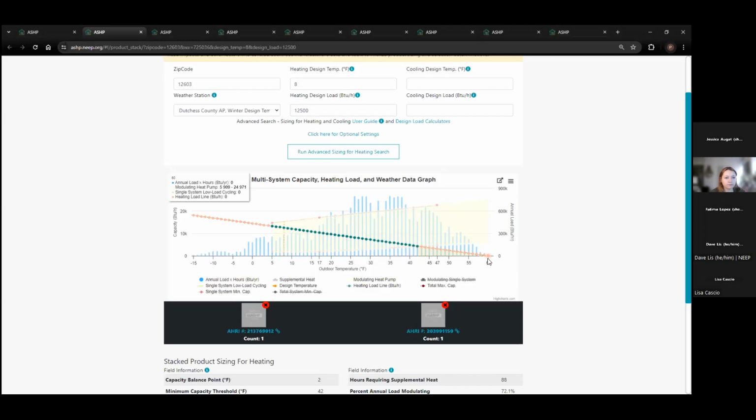So what Dean is asking is about this temperature right here, the essentially zero load point at 60 degrees. Why is this 60 and not a 72 degree temperature set point? The load at those times where it's 65 to 70 is typically almost zero. Typically the sun will account for that load, and your heat pump won't operate during those times just to bring the indoor temperature up to 72. You'll have enough internal load from the home, and external heat from the sun, to bring the home up to a comfortable indoor temperature. We've considered allowing a user to adjust that in the past, and it's just lost out to some of the other upgrades we've had.